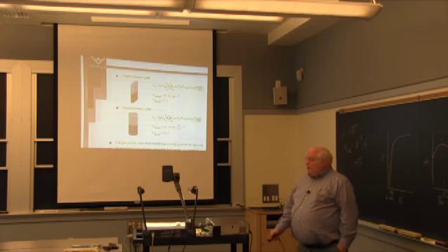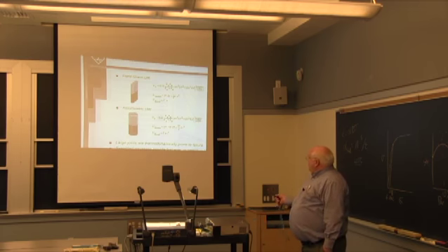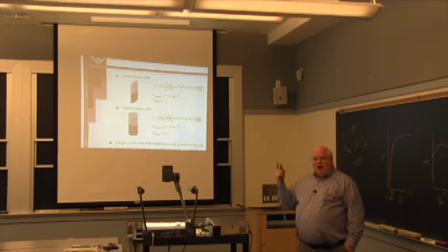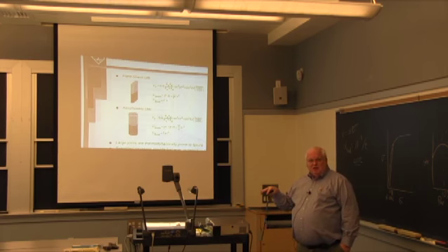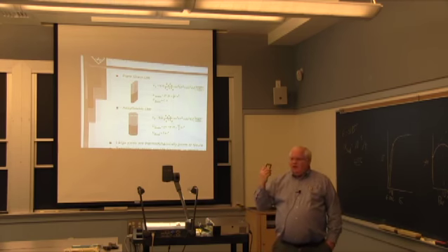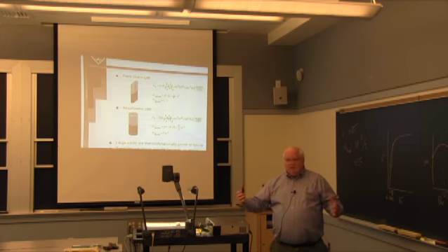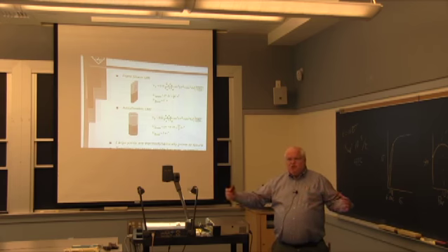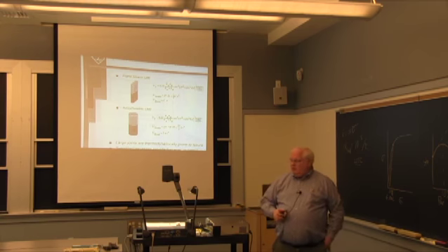The point is, strain energy always goes one dimension higher than the bonding strength, which means you can always bond small things, but you can't bond big areas because strain energy will kill you. Just think of it as stretching a spring bigger and bigger, and there's more and more energy there, and eventually it's going to fall apart.